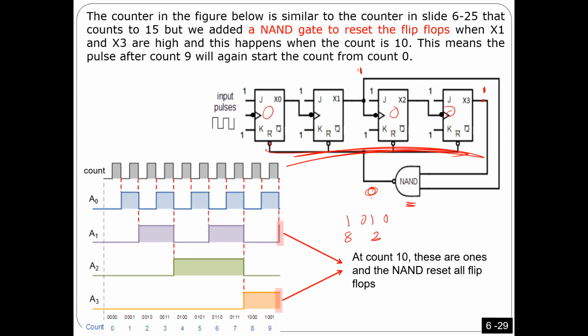You can just twist this idea a little bit. What if I want a counter that counts, for example, from 0 to 11 for some reason, and then after 11, 0 again? Very simple. I can use the same idea here. This one can count from 0 to 15, and then I can force it, once it becomes 11, to reset all the flip-flops. Any questions? Okay, thanks.